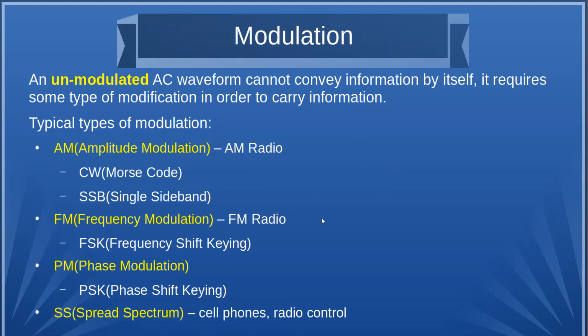Next, we have frequency modulation, where we shift the frequency with the modulating signal, usually audio, but it can be digital. And in the case of a lot of the digital signals, what we call is frequency shift keying, where it will go into frequency steps. And we have phase modulation, which is very similar to frequency, except we're only changing the phase of the signal.